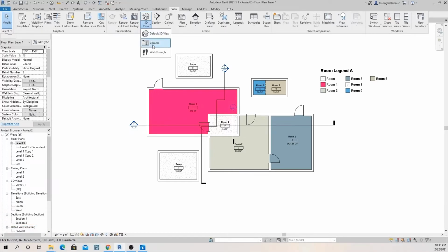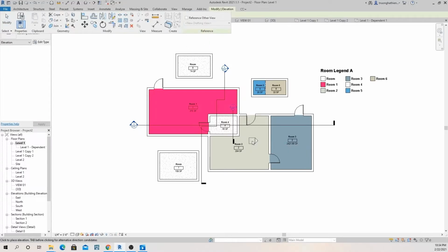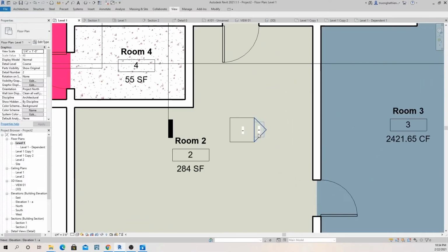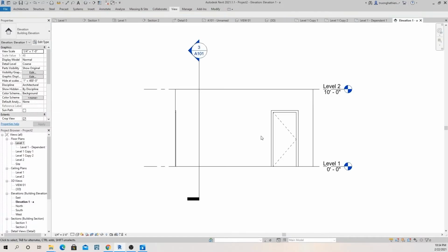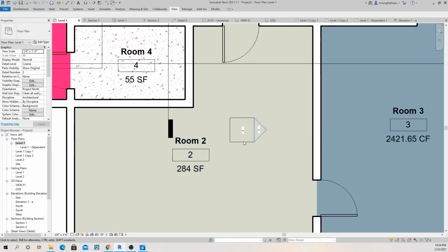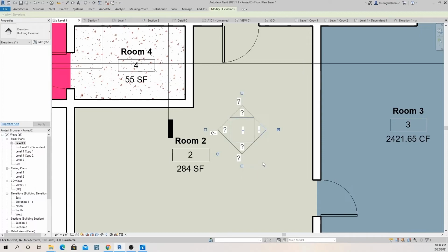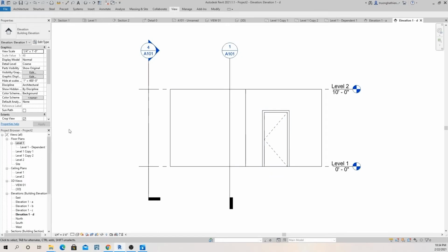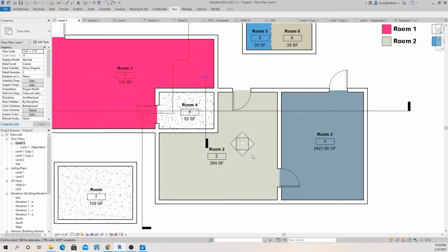I just move to how to use the camera. Sometimes you create a house with a small room. We have to move inside the room to decorate. You just place the view in the room and click on that icon. You can show exactly the elevation you want to work on. Okay, and another question mark, you can click on the box. It can show the four sides you want. Just click on the icon, you can see the side you want, and you can work on it.